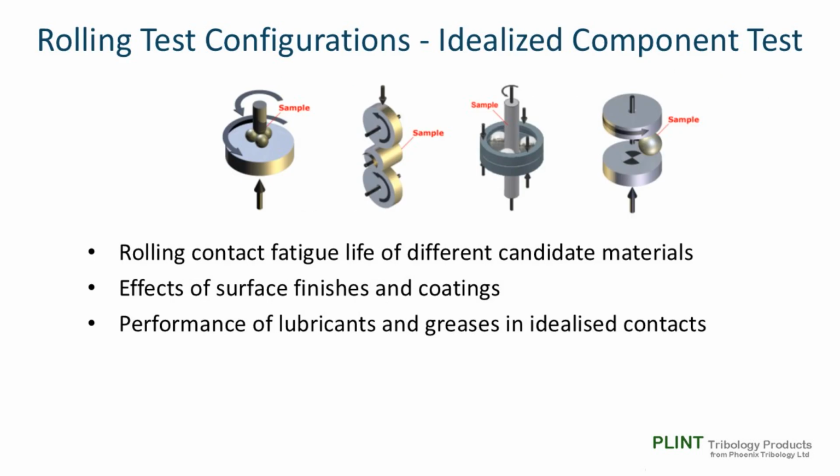These tests are aimed at stressing a single rolling element component, either a ball or a rod. These tests are used for investigating rolling contact fatigue life of different candidate materials, effects of surface finish and coatings, performance of lubricants and greases in idealized contacts.